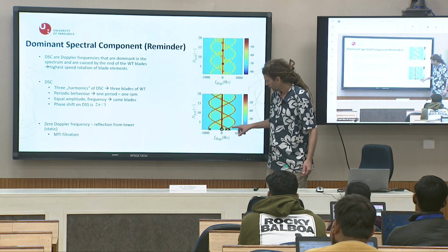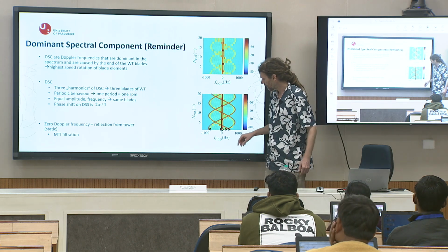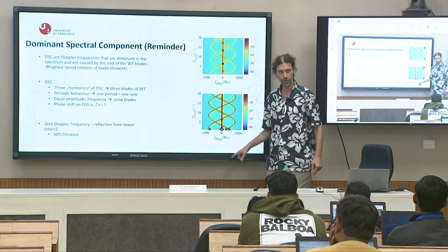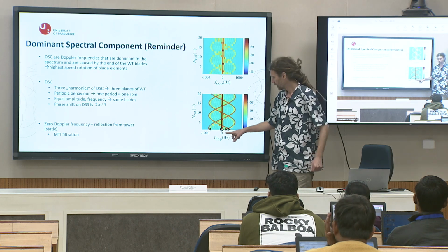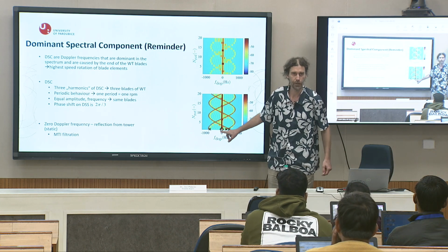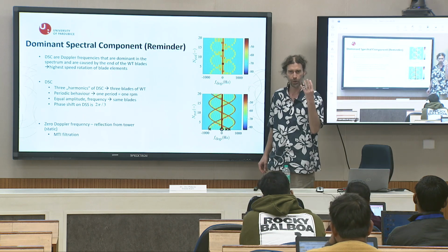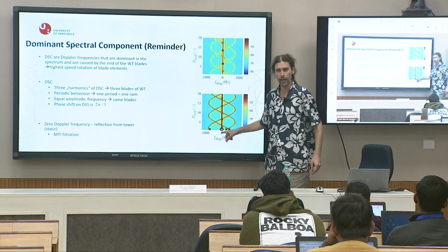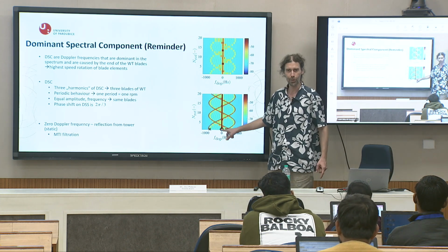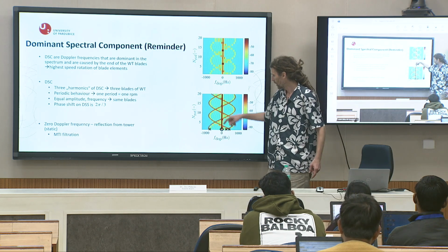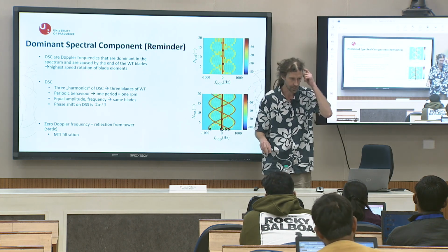It is the highest Doppler frequency in our reflected signal, but in case we don't remove the zero Doppler frequency, for the algorithm this will be like the next frequency, or zero Doppler, if you get my point. So it will not be 3 points but 4 points, and it will be really strong. So the mitigation algorithm will focus almost always on this point. So we need to remove it, and then it will focus only on the 3 exact points that we need.